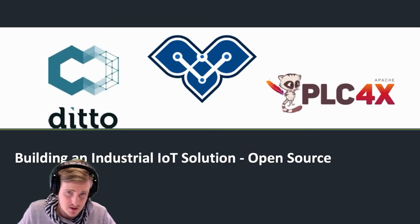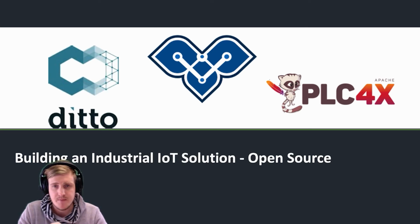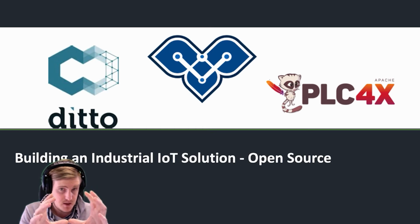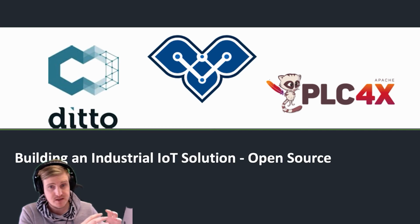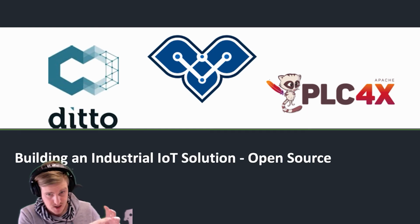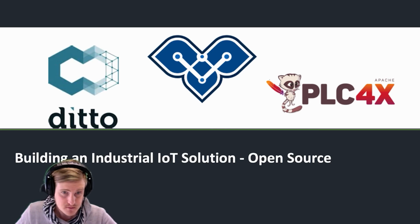But going away from PLC4X, now going over to the Industrial IoT Solution. The scratch implementation we have done basically has this idea that you have one place where you define your machine, what capability it has, what measurement drivers it has, which is done in Vorto. Then you have Ditto, where all the information should be stored, and then you have some kind of gateway near the machine where PLC4X is running, which on one side fetches data from Vorto to know what exactly to read and how to name things, and then pushes it over to Ditto.